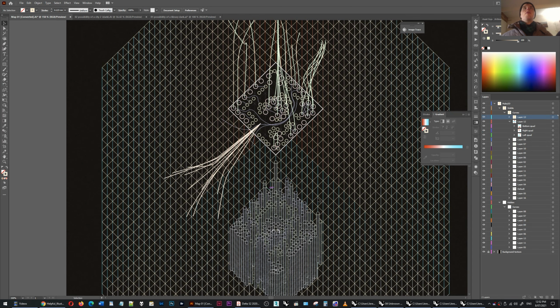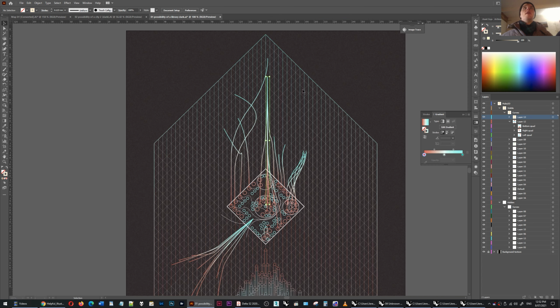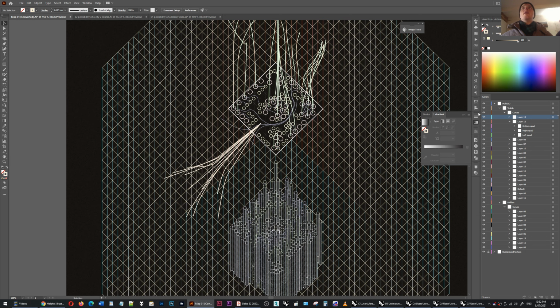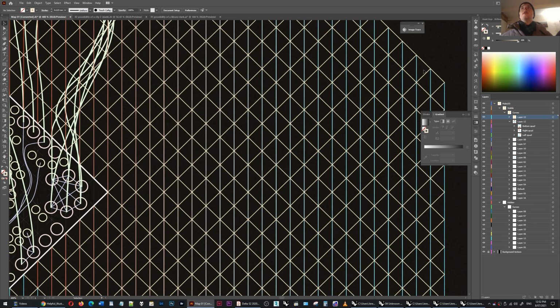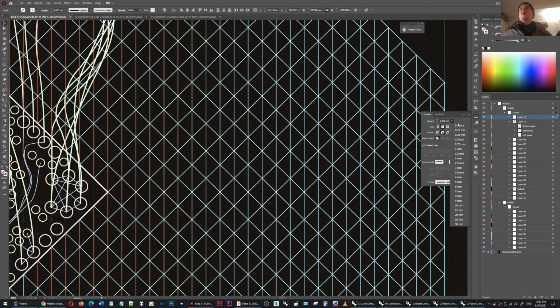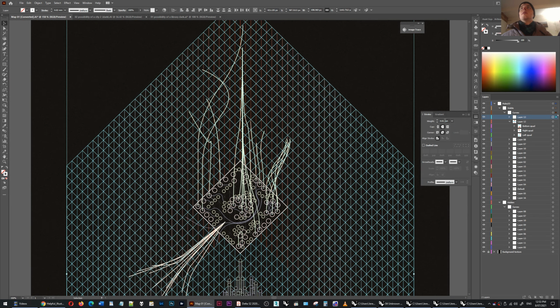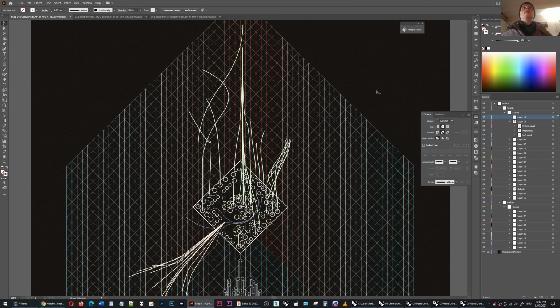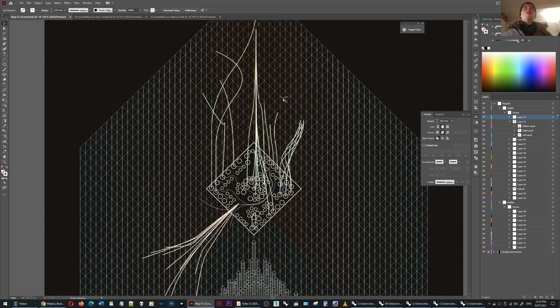I'm now going to go through the rest of the image and emulate what I created in the first place, which was here, and I'll show you how I did that. Some of the things that I've seen are, for example, these lines here, these diamonds. I'm going to select that layer, make them all white, and make them a lot finer. So go to line weight, maybe make that 0.07. This is where you're really just playing with things until you get it right.